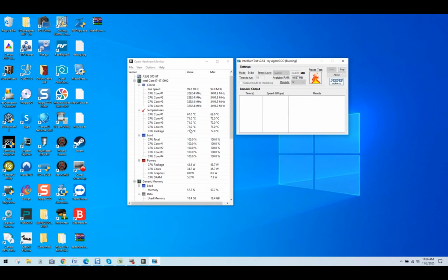The main thing is that you pay attention to everything we have here. If you're dealing with an older PC, make sure everything with your heatsink around your CPU is clean. Dust will negate any cooling. Make sure all of our cooling fins are clean, and make sure all the memory is clean. I've done a video on DeoxIT. This is where all those neat little electronic additives come into play, because all of this will aid in making everything as stable as possible in the long run. Because again, it's not one variable, it's all of them.